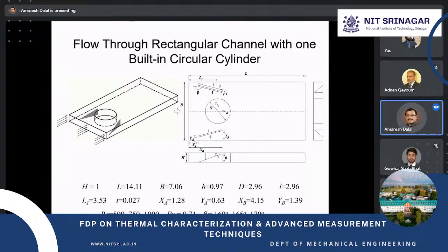Okay, so you can see that it will act as a nozzle. The area is decreasing, because this is a solid surface and this is also solid. So in some way a nozzle kind of arrangement will be formed, right? As the area decreases, to have the same flow rate, meaning volume flow rate, the velocity should increase. So that way obviously it will act with high velocity and it will enhance heat transfer, and there will also be formation of longitudinal vortices and horseshoe vortices.